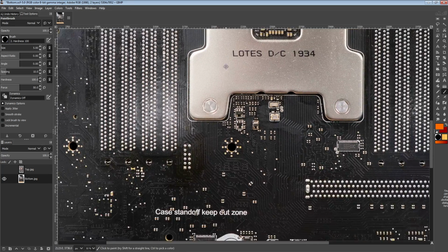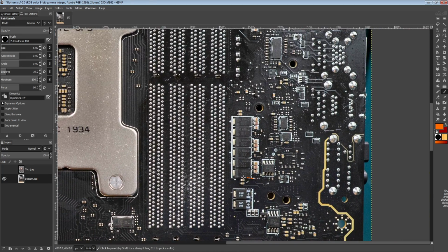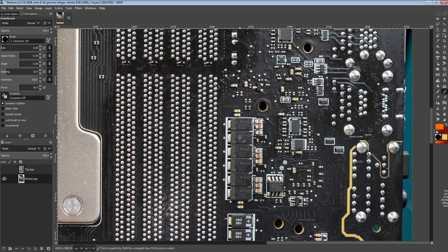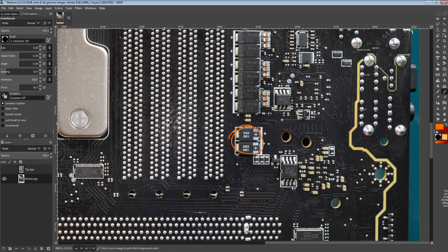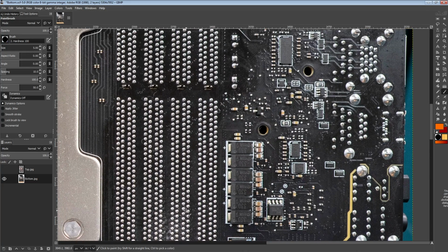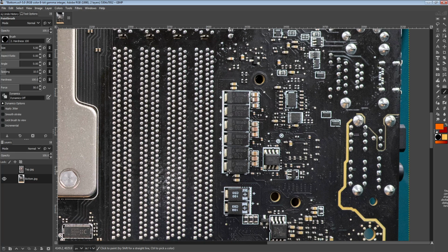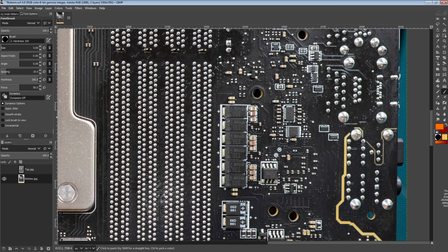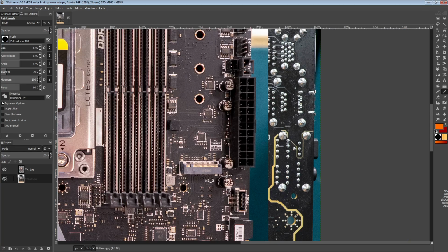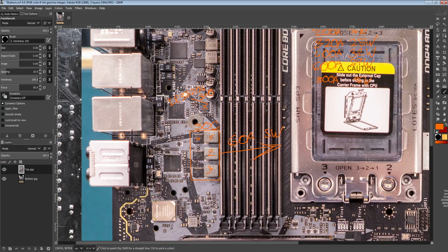What's kind of noteworthy about the SOC VRM is that it is all polymer SMD capacitors for the output filtering. Aluminum polymers at that. Like, these are technically tantalum polymers, so saying polymer is just like, well, that's a lot of different types of capacitors there. So yeah, aluminum polymer SMD, 2-terminal variant, and these are basically just better ESL, better ESR than your through-hole capacitors. Though as far as I'm concerned, the main reason we're seeing these here is not for electrical design considerations. It's just that through-hole ones don't fit on the back of the board. There's not enough space in this area of the motherboard to use the larger variant, so that's why they went with the SMD ones.